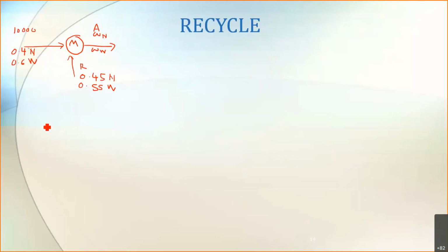So before we can start solving for this one, it is always advisable, it is always recommended that we do degree of freedom. Now, number of unknowns is equal to R, A, W, and mass fraction of NaOH and mass fraction of water. So I have 4 unknowns.